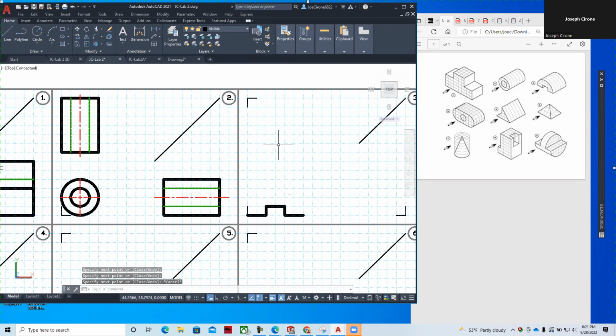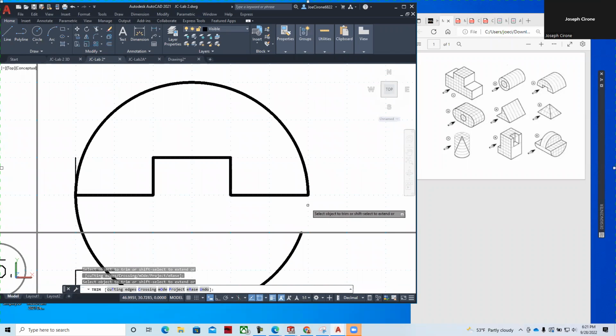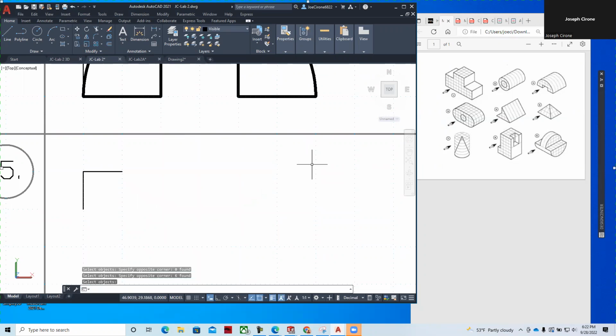And then as we create the arc for that, I'm just going to draw it with the circle from the center. And I'm going to trim it. I prefer to draw circles and trim them than I do to draw them with arcs.